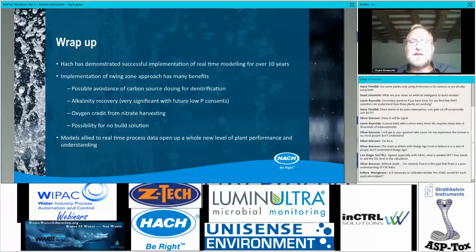It intensifies the treatment available, and not only does it maximize the capacity of nitrification, it also minimizes your energy footprint, because you're squeezing all the value out of the nitrate when it's safe to do so.